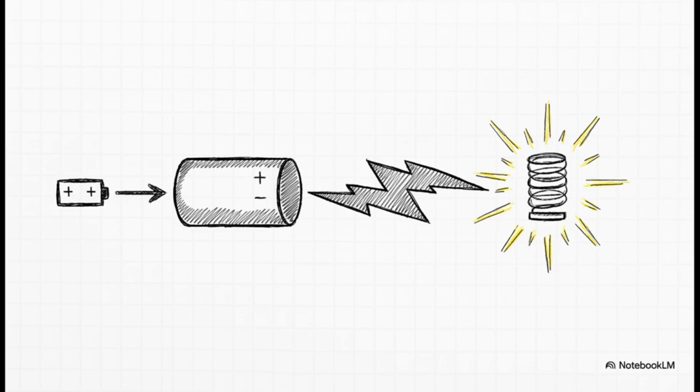We leverage this powerful relationship in high-energy systems like the aircraft strobe power supplies you'll find in ADT Chapter 33. We take these large electrolytic capacitors, charge them up to a very high voltage, and then discharge them in an instant to deliver the massive burst of current needed to ionize the xenon gas in a flash tube.